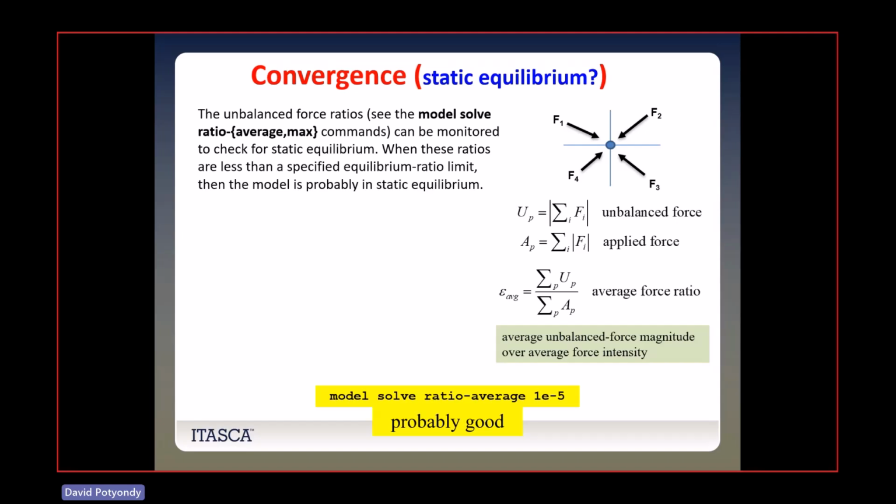So you say, okay, why don't I just run the system until all the velocities are e to the negative 13? You could do that, but it's going to take a huge number of cycles to reach that. You're going to find that by the time the velocities are maybe 1 e to the minus 6, the force chains are no longer changing, which means nothing of interest is happening. You can probably say I'm good enough, and go on to the next step. I've let them settle into gravity.